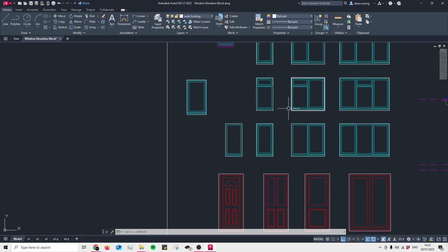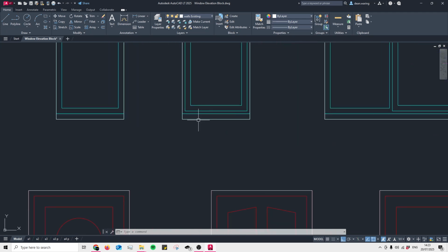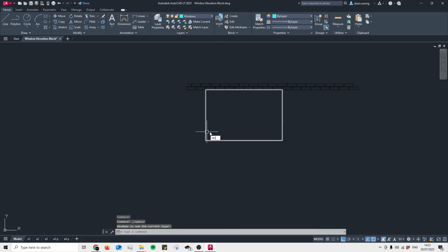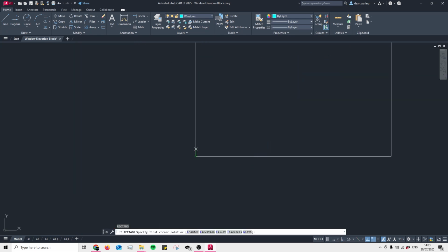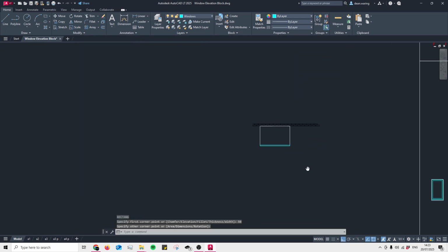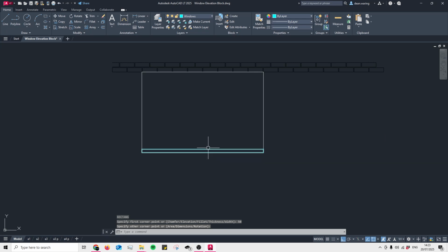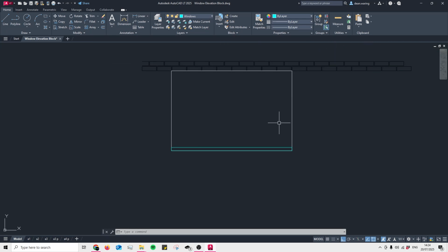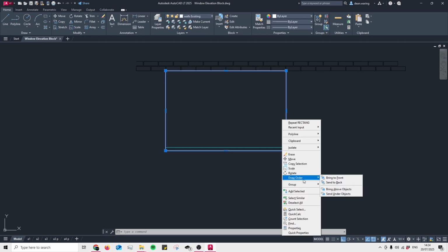Almost every single window that you'll come across will have a sill at the bottom, and this is represented as a 50mm rectangle. So put in a 50mm tall rectangle in the layer that you will be using to show that it's your window. I have a Windows layer available within this document. So now that is the simple part done, although I like to ensure that I have my white outline around the window showing, so I'll select this and I'll bring it to the front.